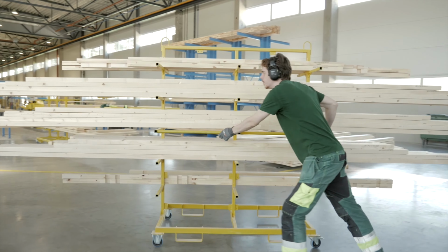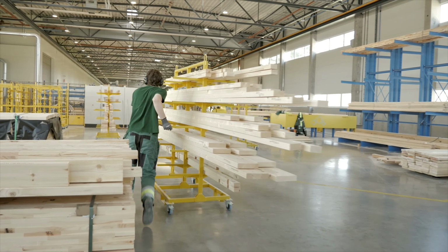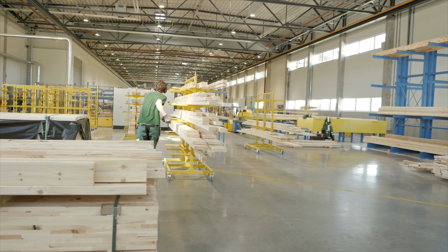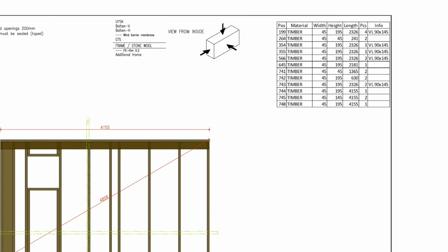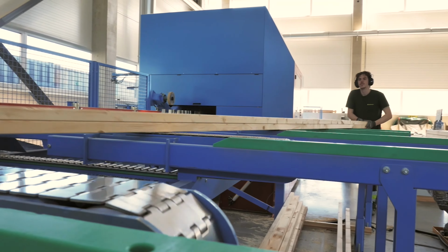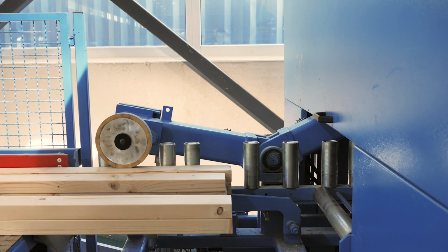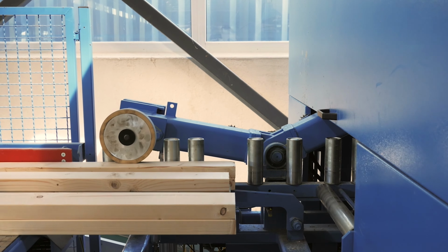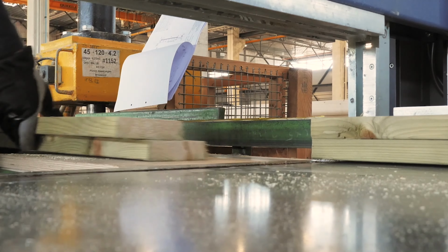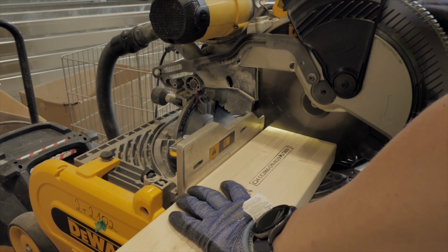To assemble the frame, components like studs, sills and lintels need to be cut out according to the drawing of the wall construction specification. There may be several options here. One option is to order correct size components directly from the wood supplier, and another option is to use an on-site woodcut machine. But in the simplest case, the necessary details can also be cut out with hand tools.